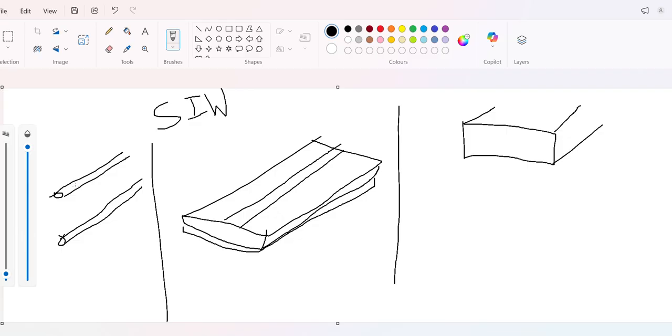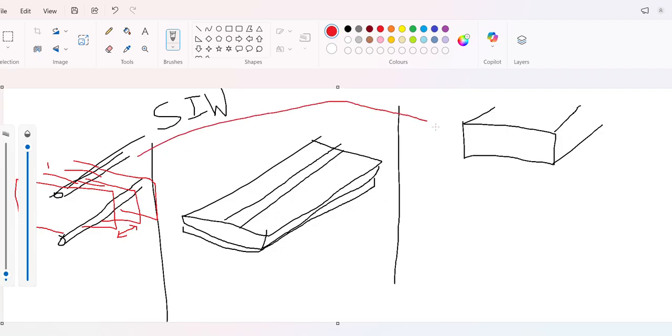In the two-way transmission line, if we connect both sides with lambda by 4 short-circuited lines, this side and this side, like this, and keep on joining them together but with length of, let's say, lambda by 10. The distance between these two short circuits should be less than lambda by 10, so that it looks like a seamless connection. This will directly emulate a metallic waveguide. You can think of it like this.